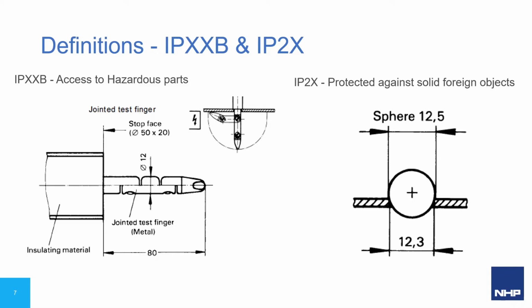As per AS 61439, any barriers must be a minimum of IP2X or IPXXB. This involves two requirements: protected against access of hazardous parts with a finger. The other requirement is protected against solid foreign objects of 12.5 mm in diameter and greater. When we are talking about form ratings, just think, if the sections are meant to be separated, ask yourself, when you have access to one section, can you touch the other section with your finger? If yes, then it fails.